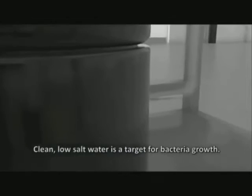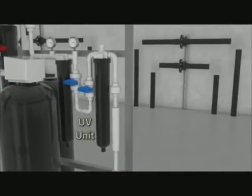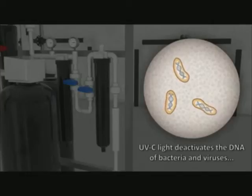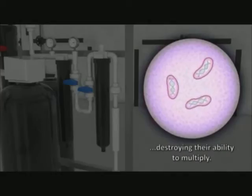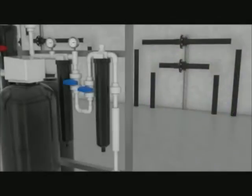The clean water low in salts, typically stored for a period of time, is a target for bacterial growth. Therefore, the process and water system includes a germicidal ultraviolet disinfection unit for bacteria control. Germicidal UVC light deactivates the DNA of bacteria, viruses, and other pathogens, and thus destroys their ability to multiply, which is critical in any process and lab use environment of RO product water.